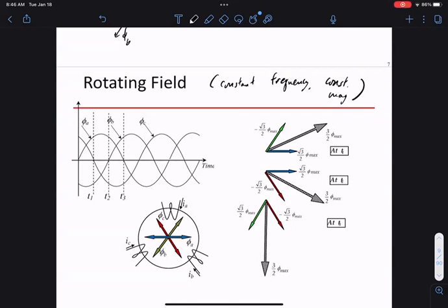So often you'll see the question, why can't we use a type 1 wind turbine directly powering a load? Because something has to set the frequency. The generator itself does not do that, so something else is doing that. So that's why we can talk about this field as a constant frequency.